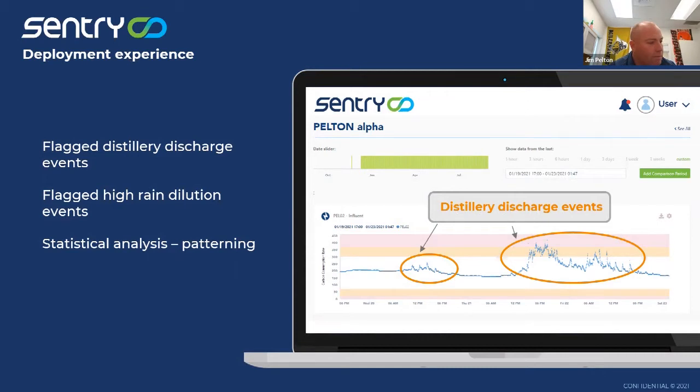The Influent probe, we started seeing good data right away. On the probe we put in the RAS pit, we actually questioned whether the probe was operating properly, because we were getting metabolic results in the single digits, between 1 and 10, where the Influent probe was showing somewhere between 200 and 400. Ultimately we moved the one from the RAS pit into the Influent channel. It almost immediately snapped back to life, showing that it was operating correctly.